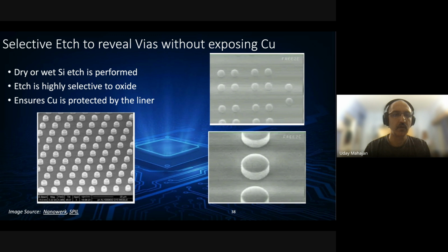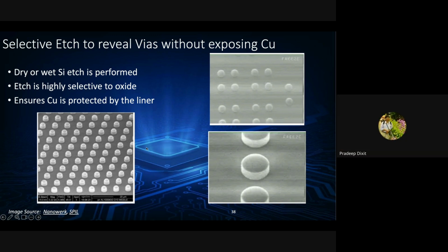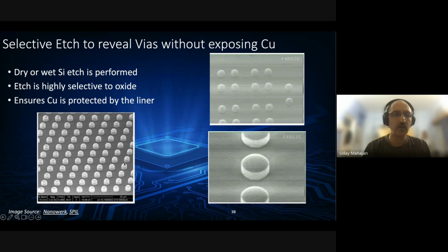And if your reveal is too little, then the TSV will get buried under the subsequent oxide layers that are deposited and will not be exposed. So those TSVs will be dead, will not become through silicon ever. If you have too much reveal, then too high a structure is jutting out and it exposes the TSV to risk of breakage. So controlling your process uniformity is extremely critical.